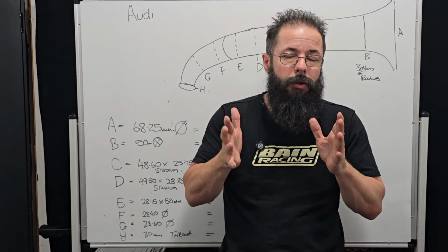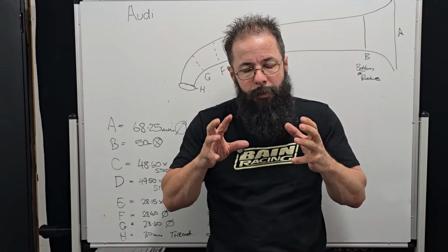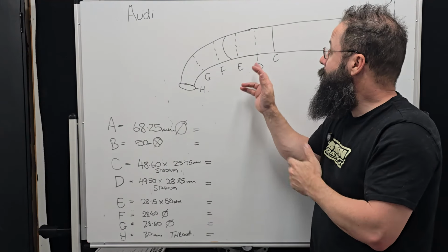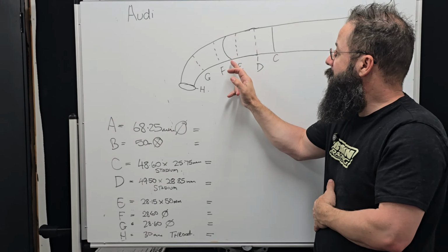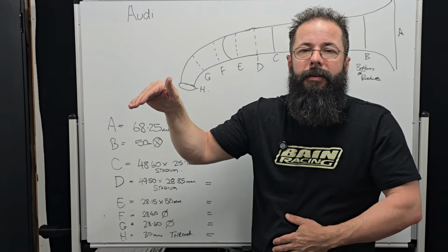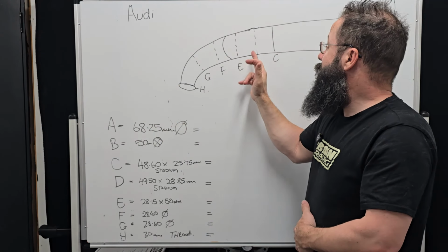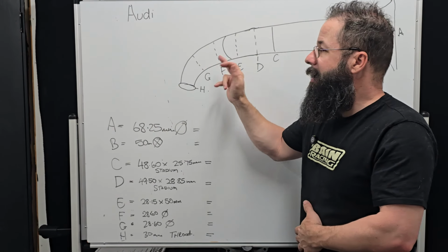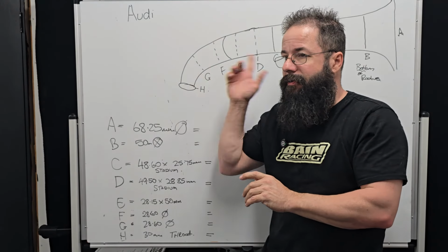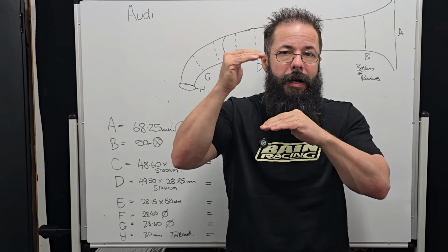And this is really, really important, because again, it's about port energy. So if this part of the port's dead and this part of the port's fast, then it's going to pull our averages down. But if this part is fast and this part is fast, now we've got a lot of port energy. Now our average velocity across that port is much, much higher.